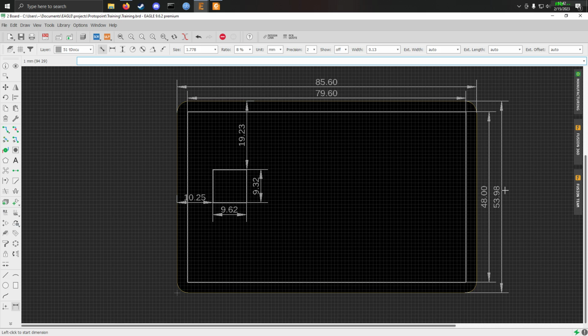Or wide, but we're not going to have the coil be exactly as wide as the card because then the edges would get damaged. So for this example, I'm going to use a 3 millimeter isolation from the edge for our coil. And this is the outer edges of the coil. So every additional turn of the coil will be moving further inward from this rectangle.